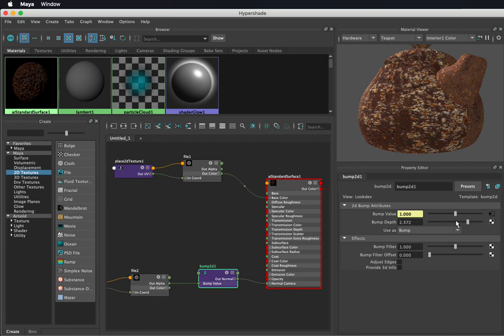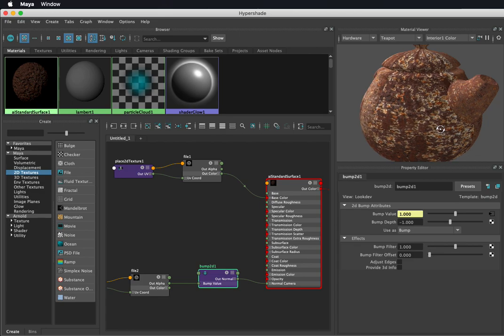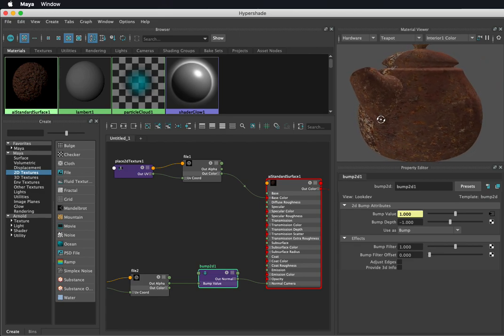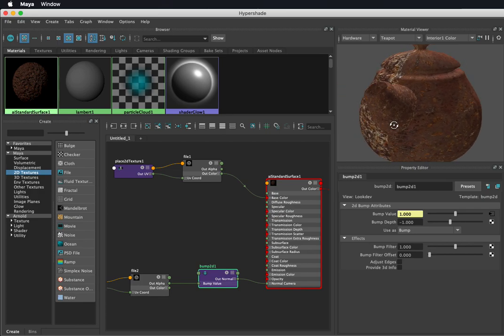You can just make it out as I switch between a bump of 5 and a bump of 0. If I go to 0, you can see it changing there. So it's a subtle difference, but a lot of these subtle differences add together to really create a sense of texture. We could even try it with a -1, because it gives us that dimpled look. All right, we're getting pretty good now, right?